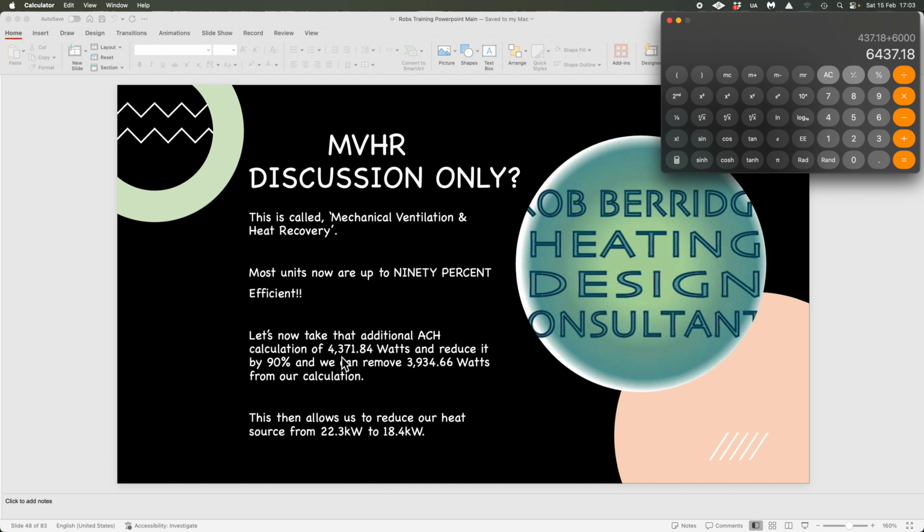But it is important, if you would kindly listen to Nathan's podcast with Barry and his father Duncan, that you'll see that the servicing and the commissioning of these is absolutely paramount. So filters need changing, fans need looking at and making sure that they're running at the correct fan speeds, and obviously each room that has your MVHR delivery points has to be adjusted correctly for the cubic meter capacity of that room.